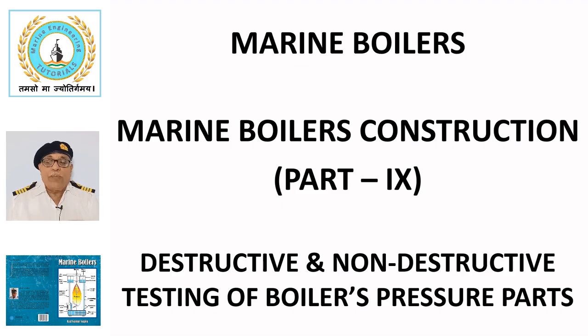Next, we will explore the procedure of non-destructive testing to examine the crystal structure of metal to check welding and heat treatment defects. Finally, we will study the hydrostatic testing procedure to confirm that the boiler can withstand the design pressure. Let us now go through each of these topics one by one in the following slides.